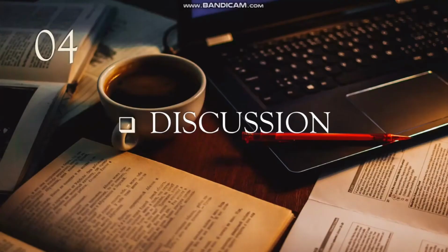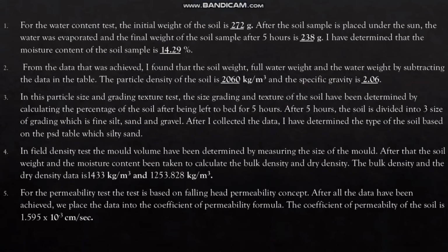Now for the discussion. The moisture content that we got is 14.29%. The particle density of the soil is 2060 kg per meter cube and the specific gravity is 2.06. The type of soil based on the particle size grading and texture test is silty sand. The bulk density is 1433 kg per meter cube and the dry density is 1253.828 kg per meter cube from the field density test. For the permeability test, we got 1.595 times 10 to the power of negative 3 centimeters per second.